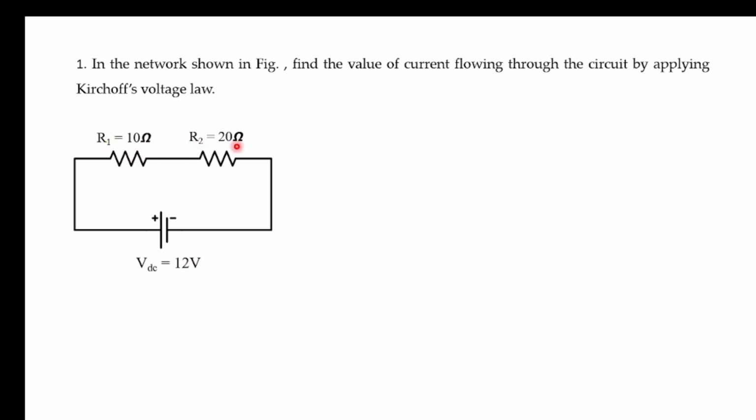So now whenever the voltage is applied across the circuit, current will start flowing from the positive terminal. So we should always mark it in such a way that it should flow from the positive terminal of the battery. Okay. So now we have to assume the current to be flowing in the clockwise direction inside this particular loop. We have only one loop and so we have one current. This current is assumed to be flowing in the clockwise direction.